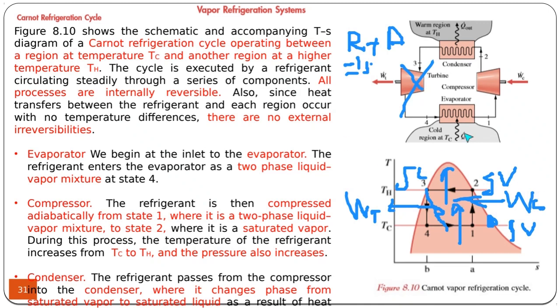If I repeat, the compressor cannot be operated using a mixture, so the inlet of the compressor must be saturated vapor.